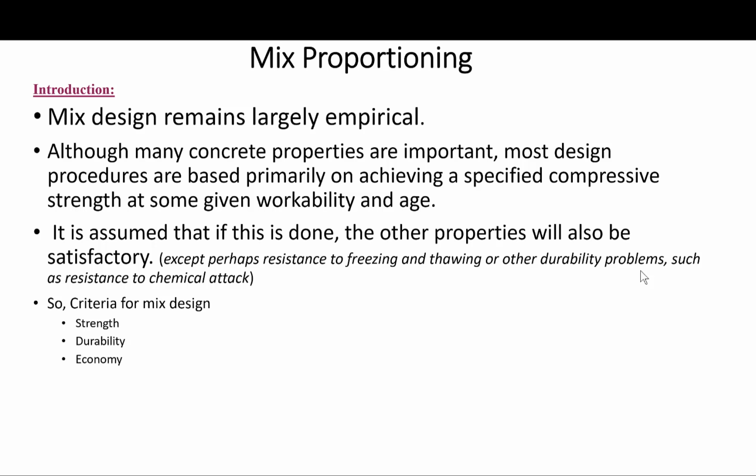There's more to it than that, but at least this is the basic process that will get you to the starting point to adjust the mix any way you want after that. So basically, the criteria for the mix design are the strength, durability, and economy.